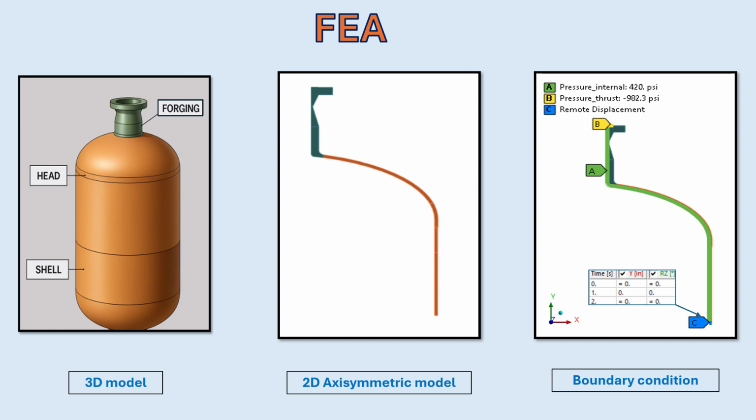To perform the evaluation, we developed a 2D axisymmetric model. The 2D model is sufficient for this axisymmetric geometry and saves a lot of computation time while accurately representing the pressure, loading, and boundary conditions.